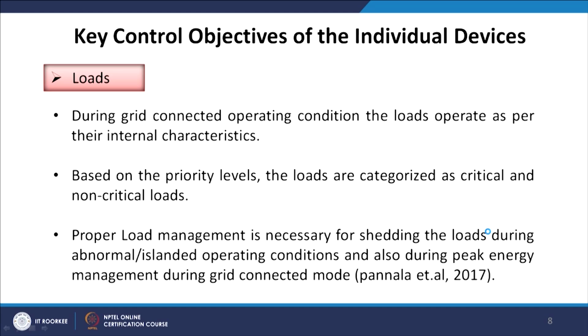So, indirectly the storage energy must be matched to my critical loads during peak hours when renewable generation is not available. Proper load management is necessary for setting the loads during abnormal islanded operating conditions and also during peak energy management in grid connected mode.